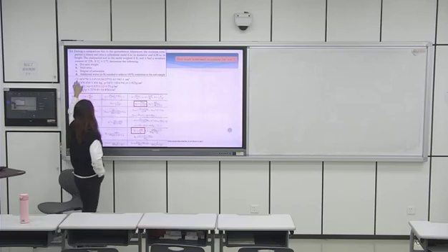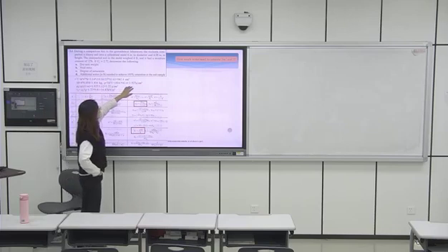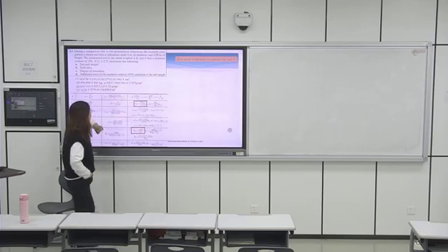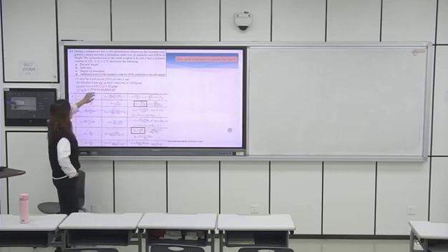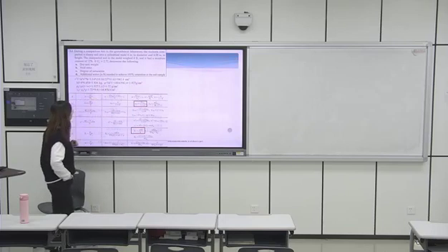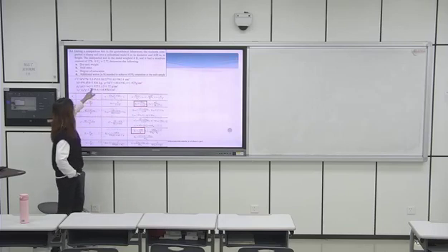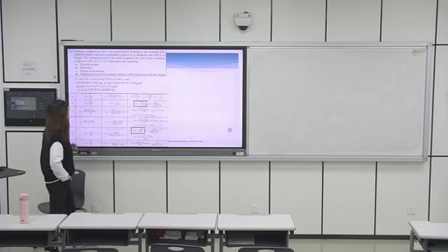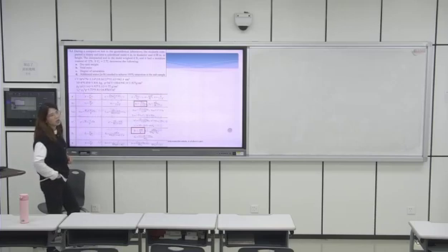And we know mass, we know volume, then we can calculate density, right, in here. And we know the density, then we can use this to calculate the dry density. And dry density multiplied by gravity gives you the dry unit weight, right? Dry unit weight.